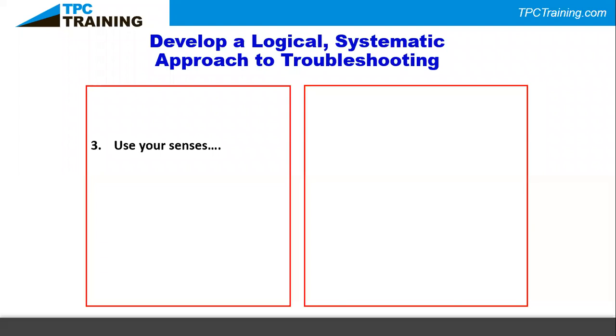So are you hearing anything? When it comes to electrical and mechanical equipment, particularly electrical equipment, if you can hear the humming of a motor, or the buzzing or movement or heat in certain equipment, electrical current is getting to that equipment because you can hear it running or trying to turn over. And that really helps on the electrical side for troubleshooting.